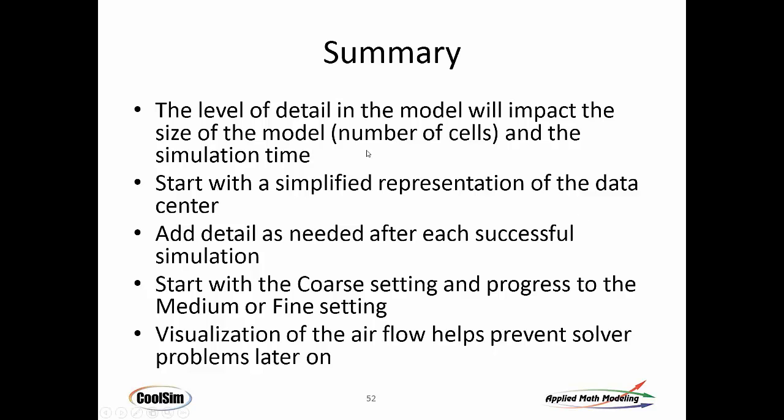Let me just summarize here. The level of detail in a model is going to impact the overall runtime because the number of cells will be proportionate. So you want to try to keep your models as simple as you possibly can and still make the point you're trying to make or get the information you're trying to get from it. Level of detail is always going to determine runtime, solve time, everything else. So start off with a simplified representation and then add detail after you get it to run and you get an overall feel for what's going on in the room.